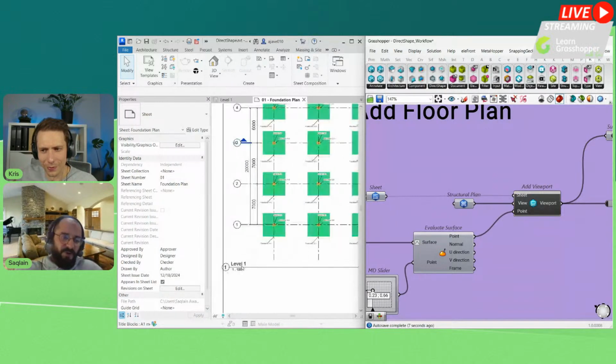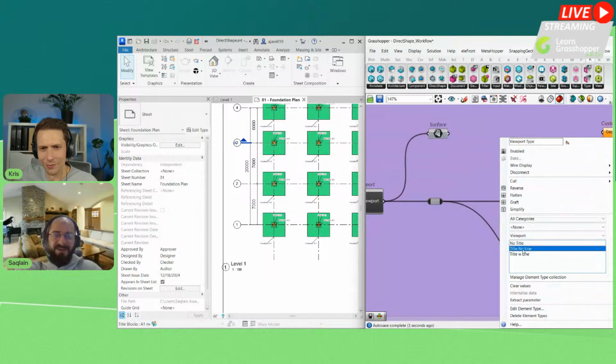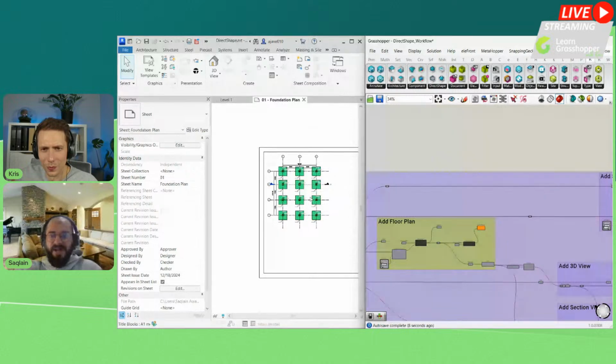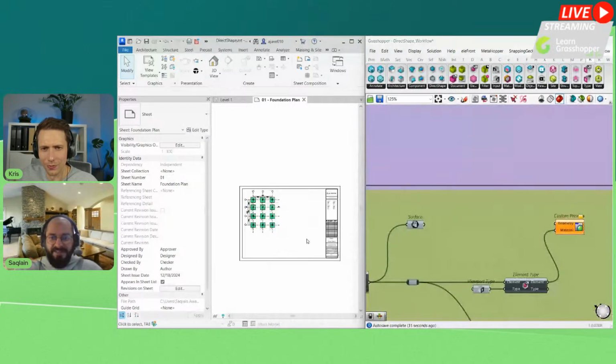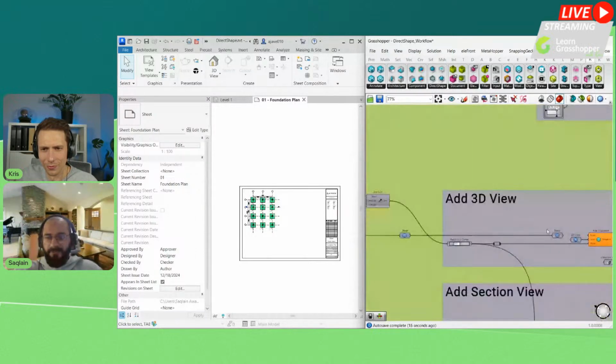And now we have this option here, like this text here. If you want to change this one, you basically use element type, and you can select if you want to show it with the title, without line, with line, or no title here. So now based on this location, I will place other plans here. I will now just go to my 3D view.